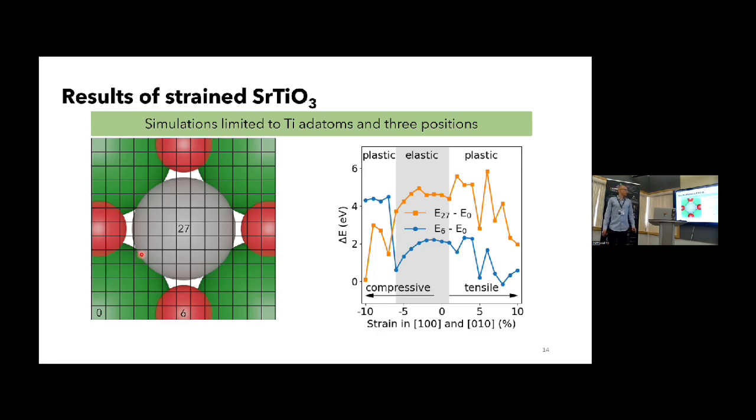And what we see, the strain, positive strain is tensile strain, and negative is the compressive strain. And what we see in the gray marked area between -6 and +1 is that we have this quadratic area, which indicates the elastic response of the system. So there are 2 main points. First of all, it's quadratic, so it indicates elastic behavior, and it's not centered at 0, 0.